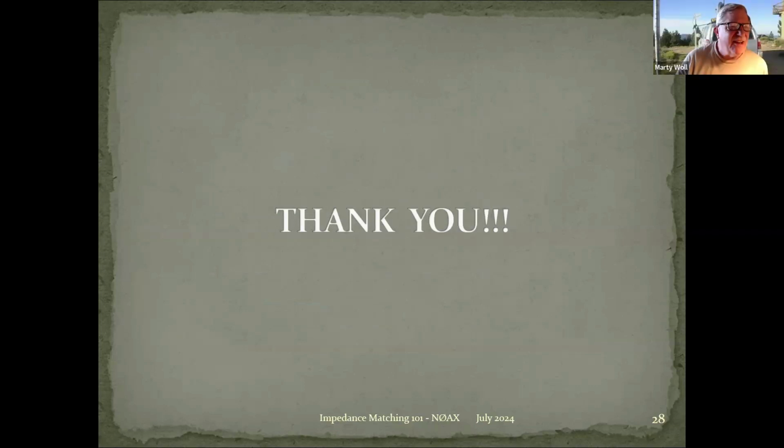Great talk, and a good reminder on all those resources that are available. You mentioned you were talking about making a choke just to keep the RF from coming down the coax, and you said, you know, wound or scramble wound. My recollection is that scramble wound will result in lower performance because you end up getting too much capacitance between the windings. One of the references that may also be applicable is the series of articles by K9YC, Jim Brown. Yep, K9YC Jim Brown, and he definitely says these turns need to be in order, even if you have to overlap at the end, but not scramble wound.